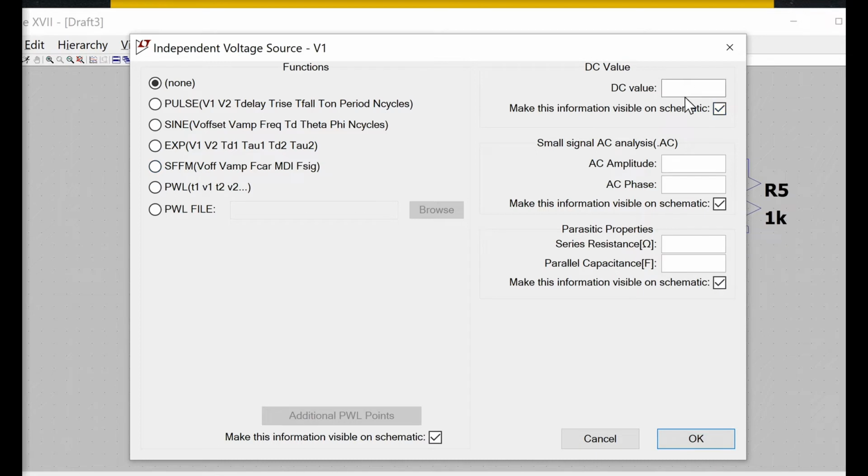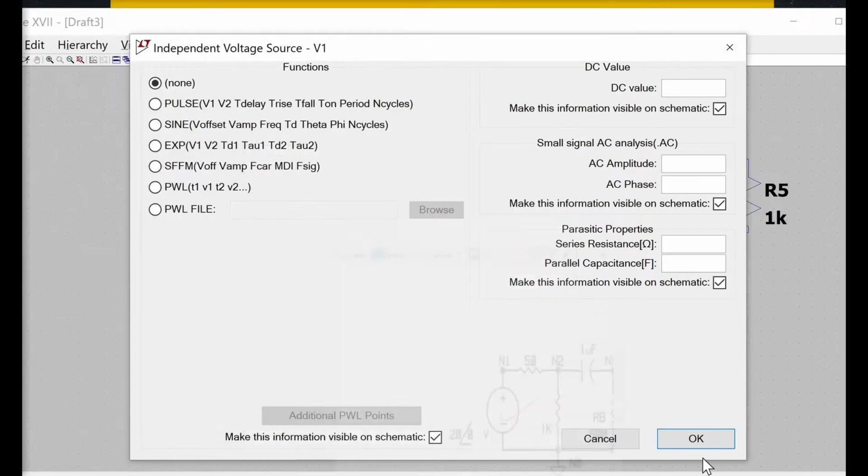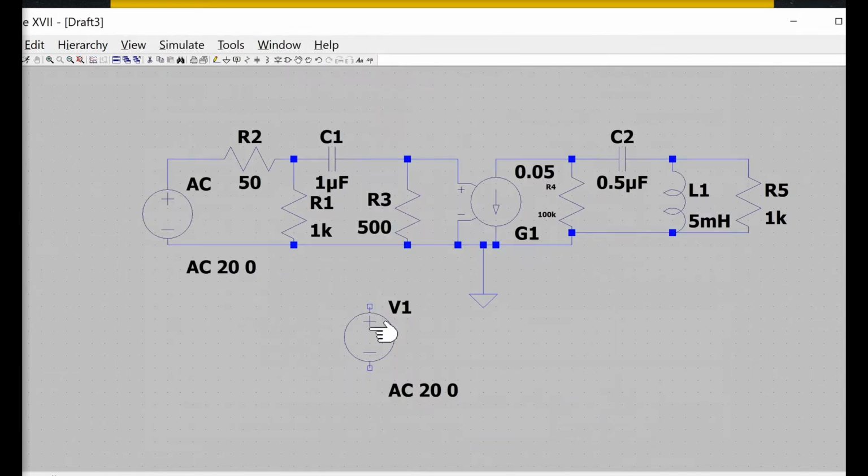I'm just going to take an easier way, which is a very simple way to show, because our circuit shows us accordingly. You can see over here it's a 20-volt amplitude, and the phase, right? These options let you select an amplitude and also the phase. So what you have to do is select just the amplitude and then the phase, and if you click OK, then this becomes an AC source. Simple as that. So that's what I did right over here, okay?